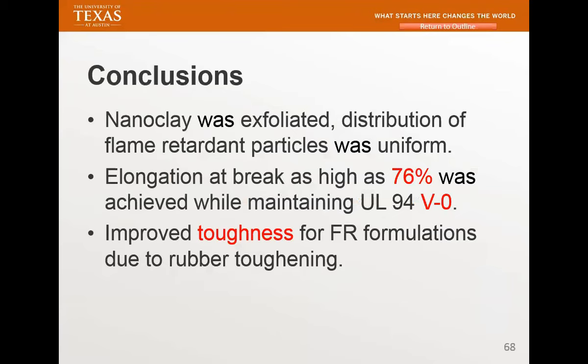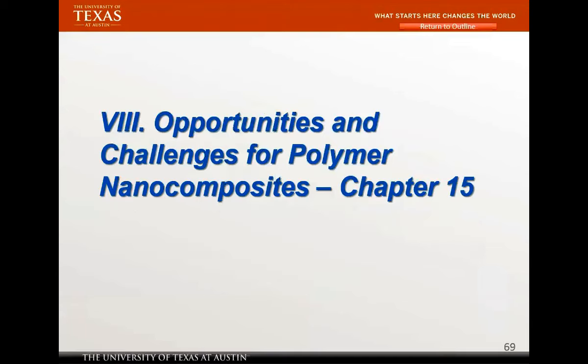You could never get to neat. You're kidding yourself if you say, oh, I'm going to bring it to neat. You look at the literature, you look at technical data sheets, a lot of them have very low elongation because you put this intumescent, all these components in there, it's going to hurt your polymer. But we were able to achieve V0 and get 76%. So that's why I got a PhD.